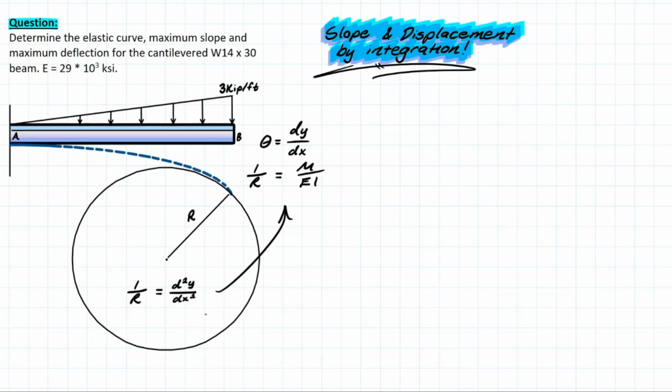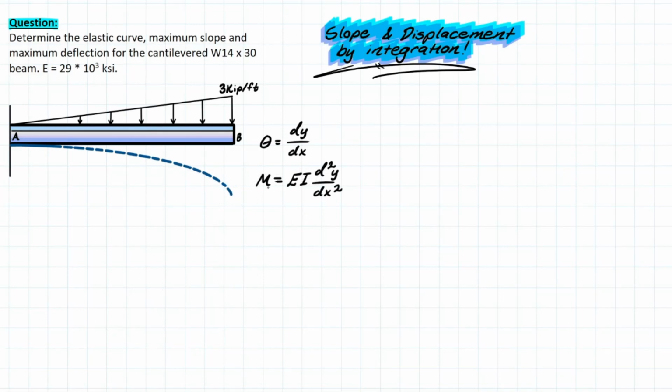Once this equation has been simplified, we're left with the curvature equaling the second derivative of our deflection. And we can then go back and plug that into our original curvature formula. Now that all of that is cleaned up, we now have a final relationship which has been reorganized for M, which allows us, in simple terms, to integrate this function twice in order to determine the deflection based on the given moment. But let's not stop there.